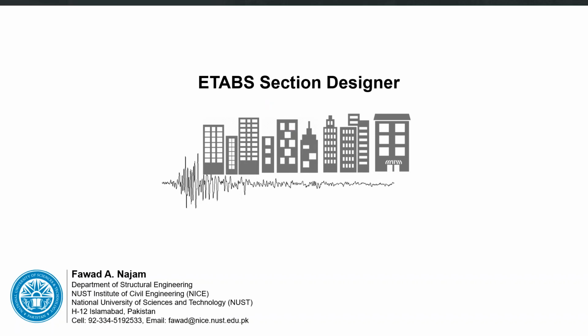Hello all. In this video we will discuss a very useful tool in ETABS, and that is called the Section Designer. This tool is used for the analysis of cross sections, to calculate the cross-sectional properties, to determine the moment-curvature relationship for a cross section, and also to calculate the axial-flexural capacity for a cross section.